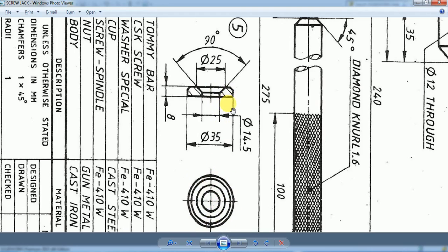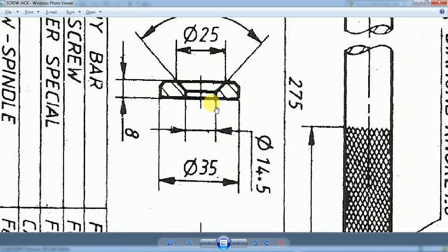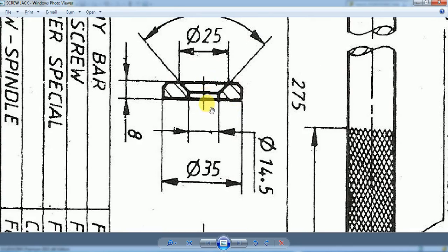Therefore, again we make use of the revolve feature to get this model. When we want the revolve feature, it is important to create half of the profile, either towards the right side of the axis or towards the left side of the axis. So here also, we create the right profile. This is the axis of the washer, and this is the right profile.